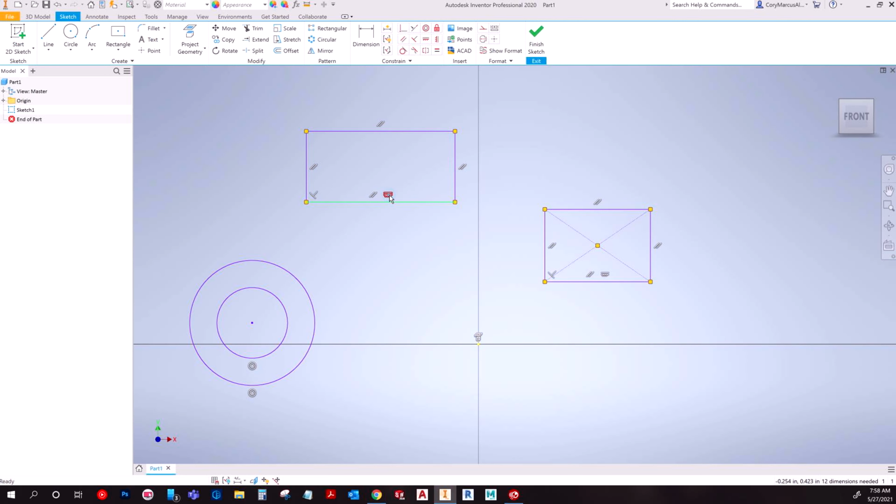It may not know that this line is horizontal, which is what this constraint is. And when you're tugging up and down, it doesn't move or try to rotate it. So if I were to pull this corner and this horizontal wasn't there, it may catch it, and it may actually pivot it around a little bit angularly. So I actually advise you to keep the constraint visibility off and tug on the points.